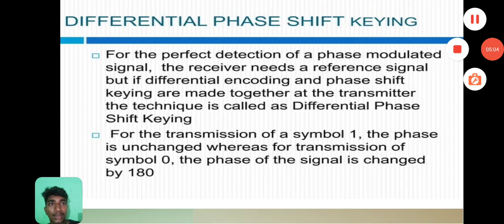Differential phase shift keying: for the perfect detection of a phase modulated signal, the receiver needs a reference signal. But if differential encoding and phase shift keying are made together at a transmitter, the technique is called differential phase shift keying.